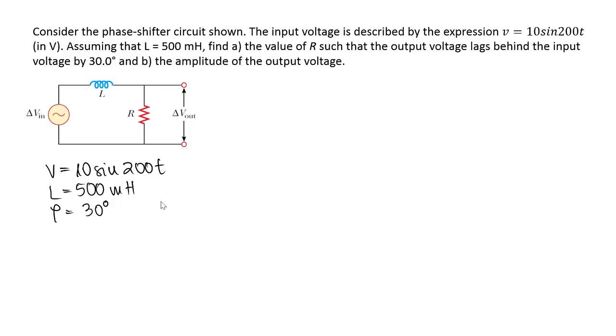Well, let's draw a phasor diagram for this simple circuit and see if we can find the resistance using the phasor diagram. To make the phasor diagram even simpler, let's consider that the current, which usually makes an angle with the horizontal axis, in this case at time t equals 0, is totally along the horizontal axis. So if the current is totally along the horizontal axis, that means that the voltage across the resistor, which is always in phase with the current, will also be along the horizontal axis. So this is the phasor for the voltage across the resistor.